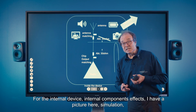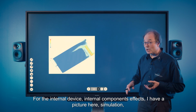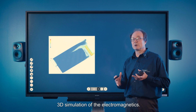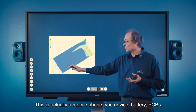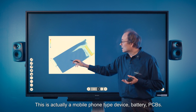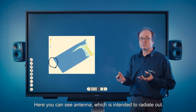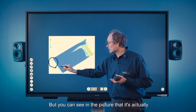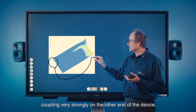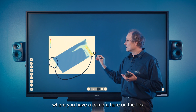For the internal components' effects, I have a picture here, a 3D simulation of the electromagnetics. This is a mobile phone type device with battery and PCBs. Here you can see the antenna, which is intended to radiate out, but you can see in the picture that it's actually coupling very strongly to the other end of the device, where you have a camera on the flex.